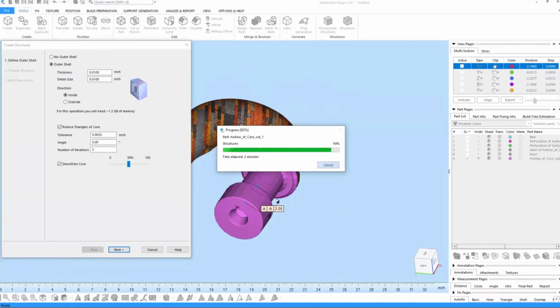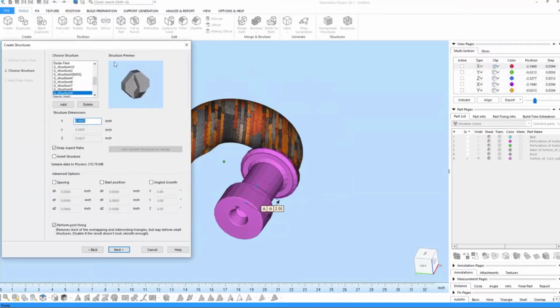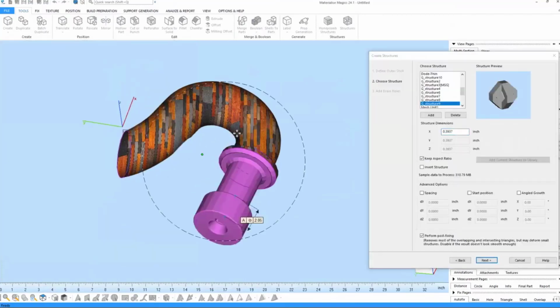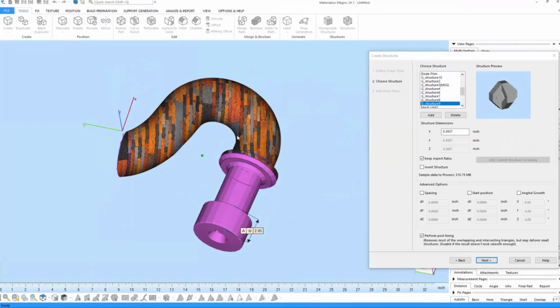Hey, Collin, we do have one question that came through while it's going. It's kind of pertaining to this model. If you want to take the second to answer it now. The image you have on your screen is a texture applied to the body, the STL. Are we able to take that out and use it on the new J55 for the full color printing? Yes, absolutely. From Magics, we can export as WRLs or VRMLs, so we can preserve that texture wrapping on our mesh data so that when we send it over to the printer, we have that still applied. We also can export as 3MFs. Awesome.